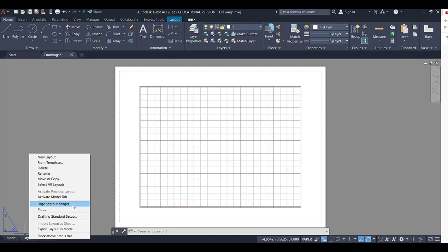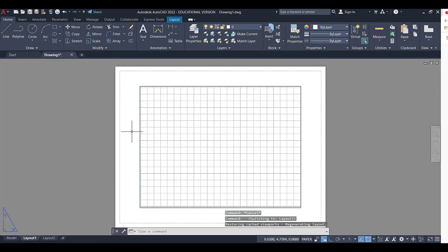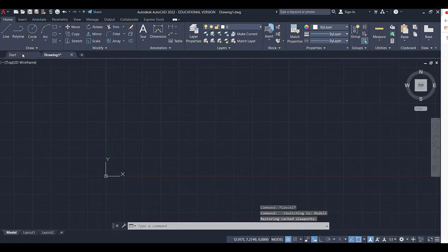Is this a huge poster board or is it a regular 8.5 by 11 piece of paper? What kind of print margins do you have? And it will use view-based to create orthographic views for you. And this is where you'll add dimensions. So you'll be able to see the size of the text with respect to how your drawing is scaled on the correct size piece of paper. So this is where you do all of the paper printing versus the model space where you draw on.